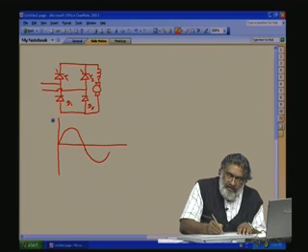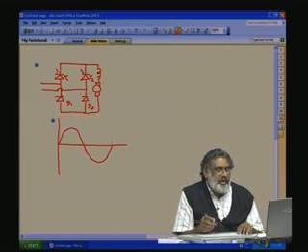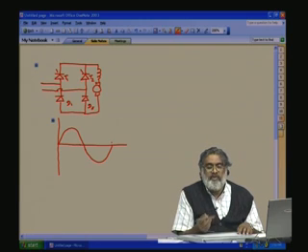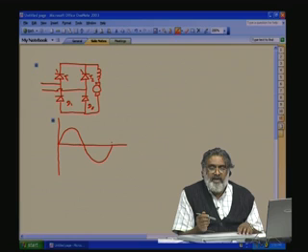We are sequentially coming to one point here. Previously, with the firing angle, the displacement keeps on increasing with respect to the firing angle. Now, with the semi converter, we made the displacement reduced to alpha by 2, that phi. Now, with the forced commutation, we made phi equal to 0.